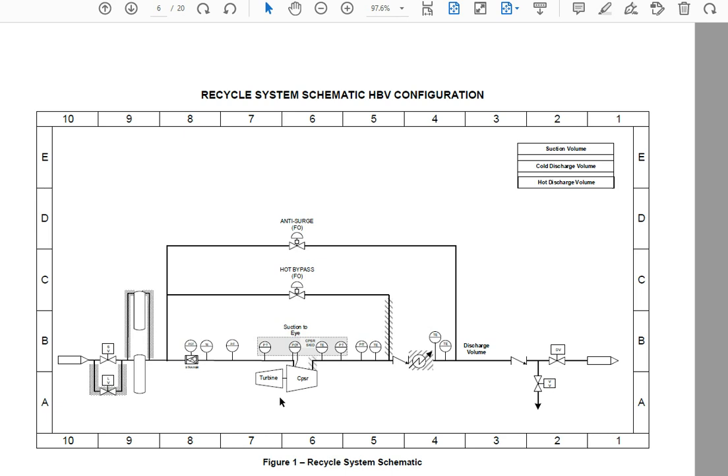That's one of the biggest variables in quantifying how quickly the machine is slowing down and how quickly the flow is diminishing. The next piece of the puzzle is the inertia of the power turbine and compressor and gearbox. So where would you get that? A torsional analysis is usually where you can turn up that information. If you don't have it, you can look at similar machines that you've worked on in the past and fudge some numbers. But really nice to have the correct inertia.